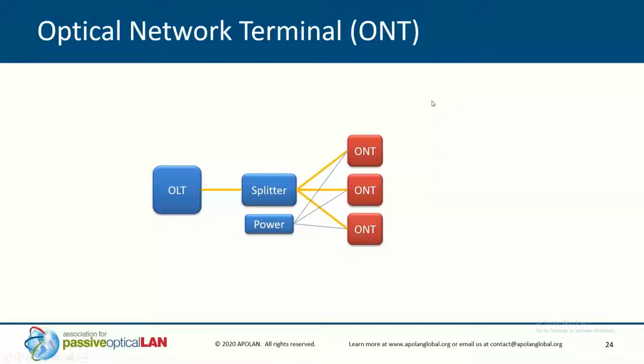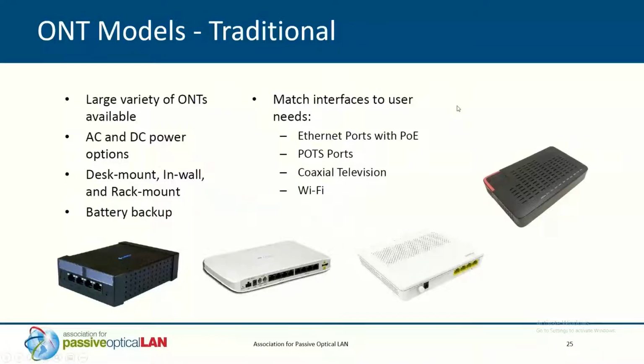Great. Okay, so again, I really do want to stress on the ONT side, even more so than the OLT, the flexibility that you're allowed in any type of PON network. So go ahead to the next slide. This is just kind of the same general outline. ONT models. All of us different vendors out there for the active components have many different form factors, many different feature sets for ONTs depending on what you're trying to do. However, at their most basic, we're talking some number of Ethernet ports.